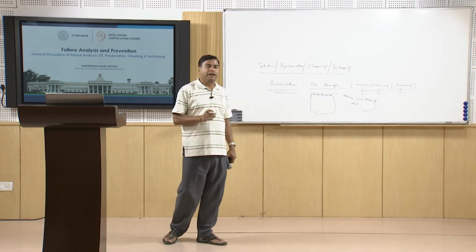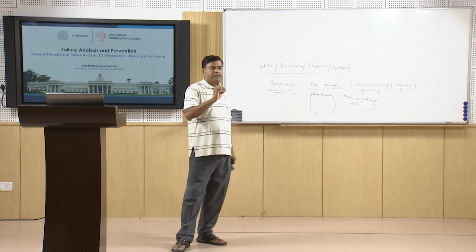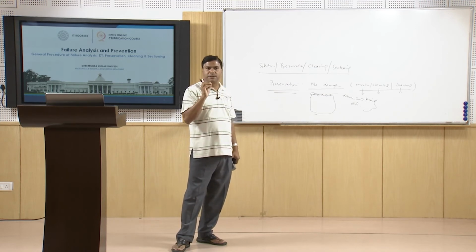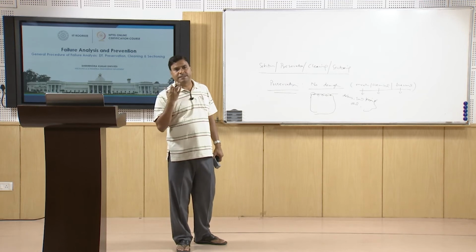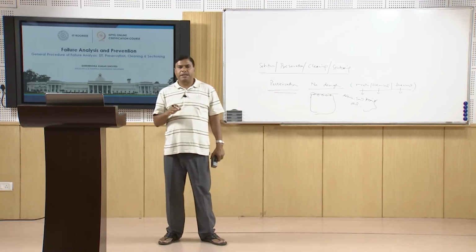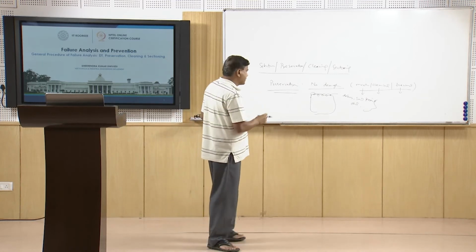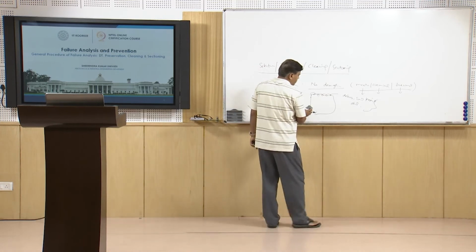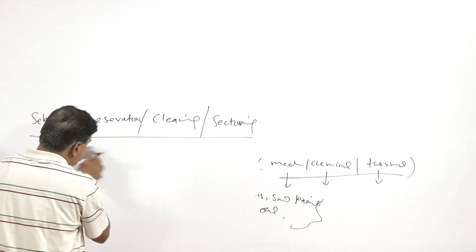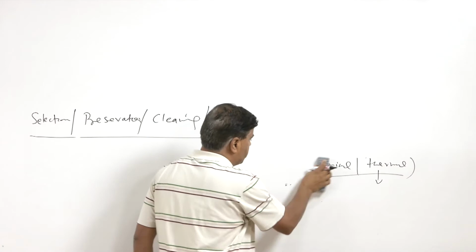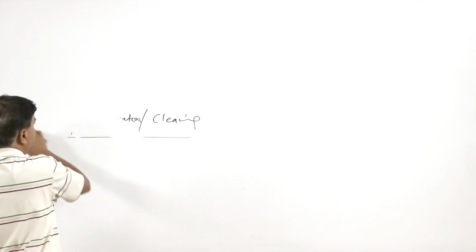There is another method, ultrasonic cleaning, where either in acetone or clean water the sample is placed and then ultrasonically treated, so that all impurities are taken off from the fracture surface and the surface is cleaned. Then there is a plastic replica method. This method is extremely good because it helps not just to clean the sample surfaces, but also to maintain a record of the things which were present on the fracture surface. So, I will explain this plastic replica method for cleaning purposes a little bit.